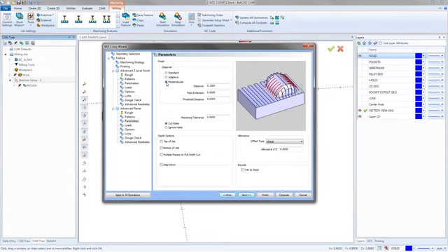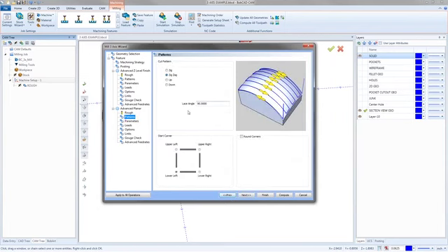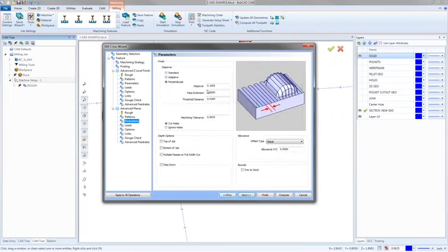So if we say the first one is to go along the Y, which is what we have, because right now we're set to 90 degrees. So 90 degrees is always along the Y. So it's going to go and cut everything that it can along the Y. And when it finishes that, it's then going to automatically go in and machine everything along the X that the Y was missing. So very awesome toolpath with this one.